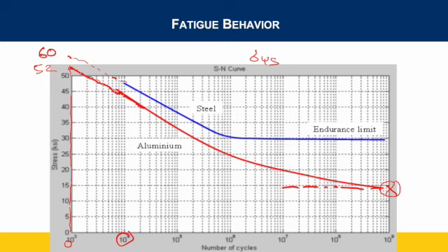This material breaks at 15, which is almost 4 times lower than its original strength. So over time, the cracks propagate in the material, the voids get bigger, surface area gets smaller, and the material will fracture. But we have other materials, like we mentioned, if the edges of the material, the sides of the cracks can blunt out, or the radius of curvature can get larger, we can actually stop the propagation.